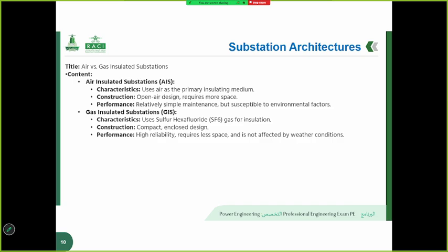Air insulated substations use ambient air as the primary insulating medium between their live electrical components. This is the traditional and most common type of substation, often seen as a large, open air network of bus bars, circuit breakers, and isolators.